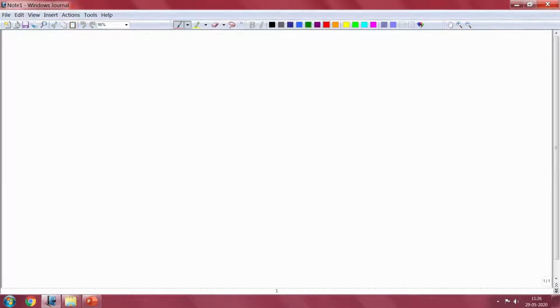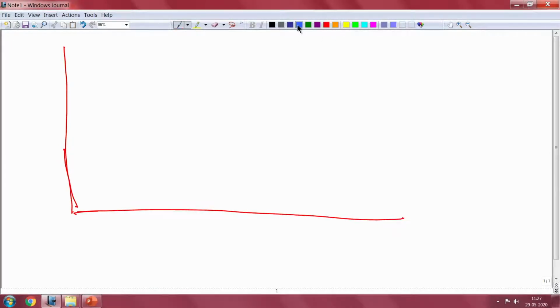I just use this board to explain the response spectrum. This is basically your plot. The period is increasing this way and the frequency is increasing here. The frequency is 0 here, and the period is the inverse. This axis will be your spectral acceleration, in g or centimeter per second squared. As we said, the displacements are constant in the low frequency range.